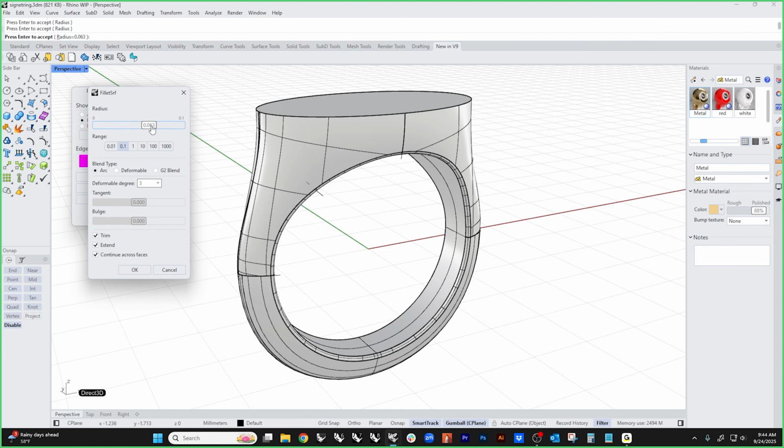So make sure that you're figuring out visually what it is, but 0.0064 is not what you want. You want 0.007, right? So that's a round number, which means they're probably going to have a cutter for it. Because if you give them a weird number and they have to make a custom cutter, they're going to strangle you. Now, we've got some other stuff in here that's interesting, right?